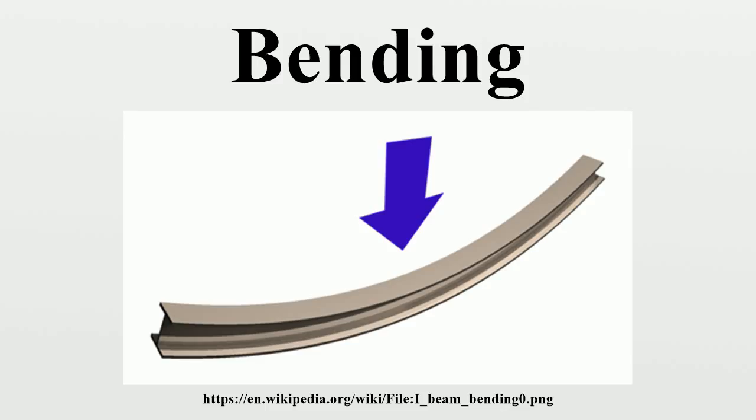The Mindlin-Reissner plate theory. Kirchhoff-Love theory of plates. The assumptions of Kirchhoff-Love theory are: straight lines normal to the mid-surface remain straight after deformation. Straight lines normal to the mid-surface remain normal to the mid-surface after deformation. The thickness of the plate does not change during a deformation.